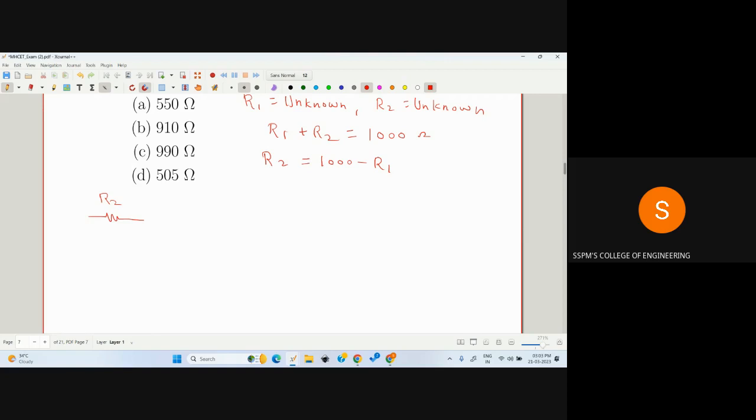The total length of wire is 100 centimeter. You can locate a galvanometer null point with the help of the jockey. Let's consider the balance or null point is L, or you may say L1. And the length of the total wire is 100 centimeter.